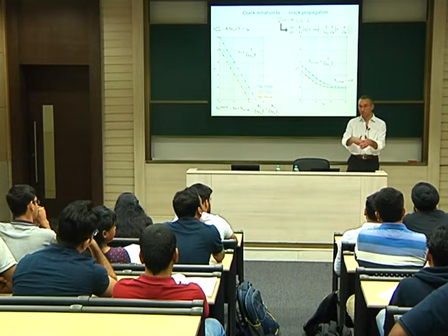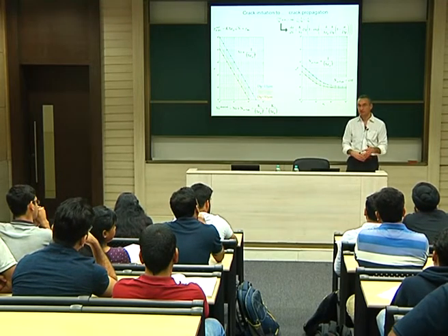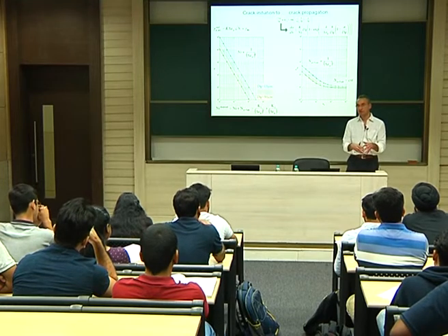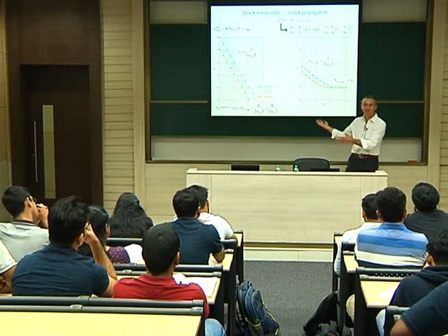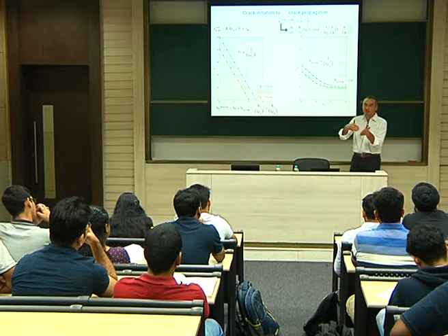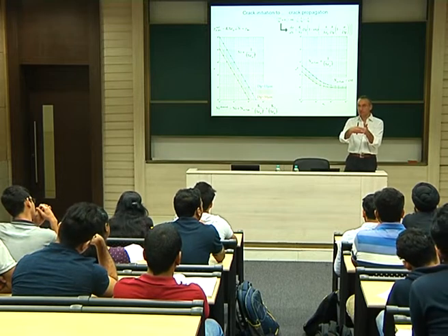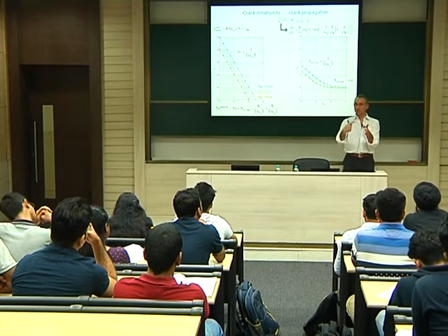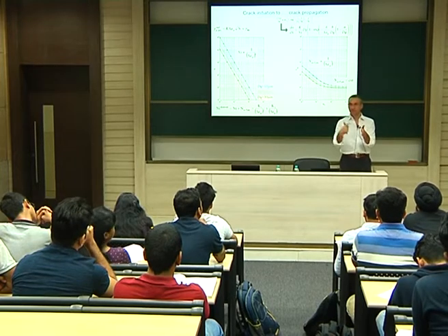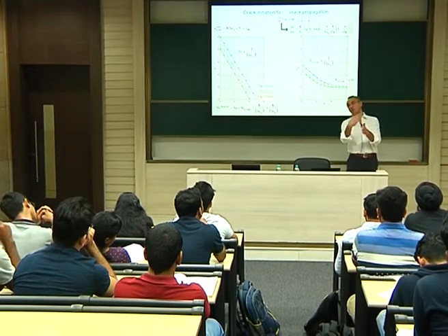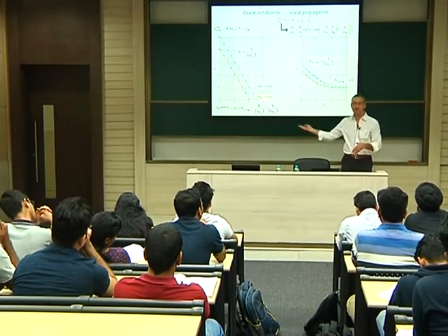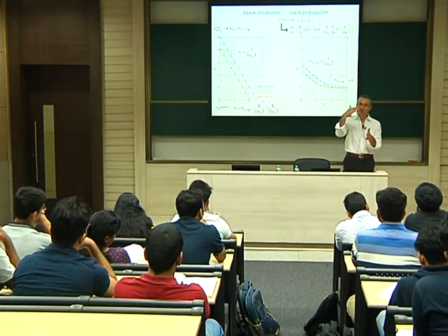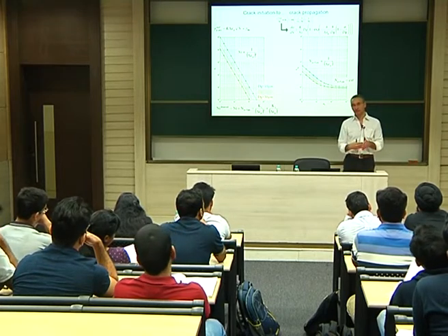It will happen at the interface. So this will happen everywhere, actually, on all the sides of the grain, not only in this direction. In reality, here it was a 2D infinite crack. So I was only investigating this side of the crack and the grain. But I agree that in the case of, how do you call this, a disc crack or penny-shaped crack, this happens on all the sides. Okay, but then the stress field is not the same. You need to change the stress field. This we didn't do. We put an infinitely long crack here.